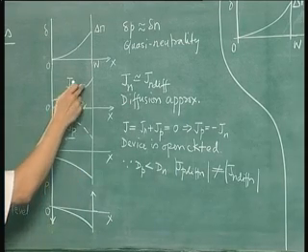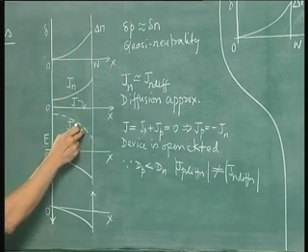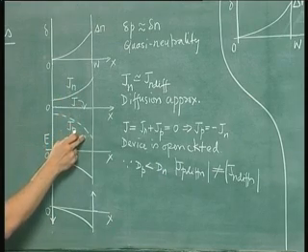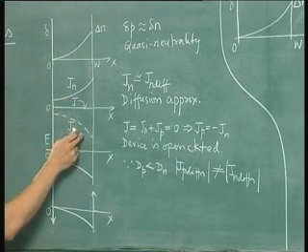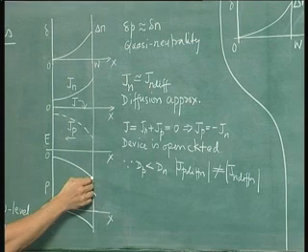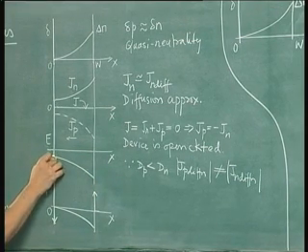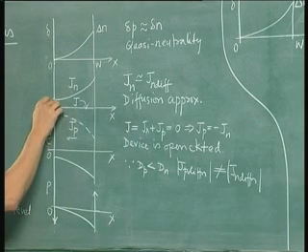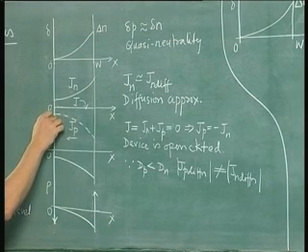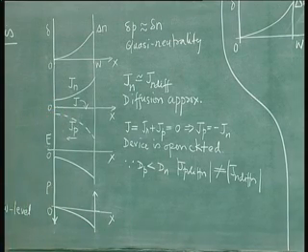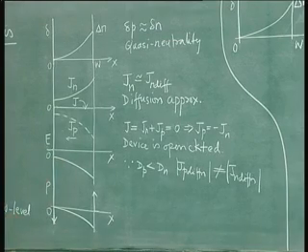Further, whenever the electron and hole currents are large, to bring hole and electron currents in step, you will need a larger electric field. That is why the electric field is larger here and it decreases progressively. Note that here the electric field is not 0 because the currents are not yet 0. So you need some electric field to keep these two currents in step. So that explains this distribution of electric field.